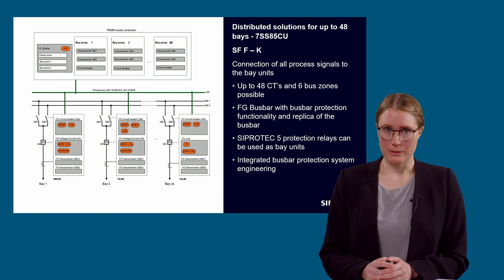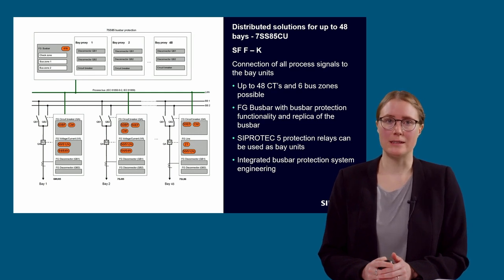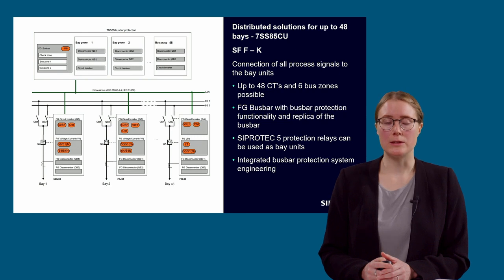The communication between the bay units and the central units is also based on IEC 61850. In the IEC 61850 system configurator, the assignment of the physical measuring points of the merging units to the central units in the sampled measured value view must be done. For this purpose, a script is provided which automatically performs the assignment according to the specifications from the single line diagram. The engineering effort is therefore significantly lower than with the IEC 61850 compliant solution.